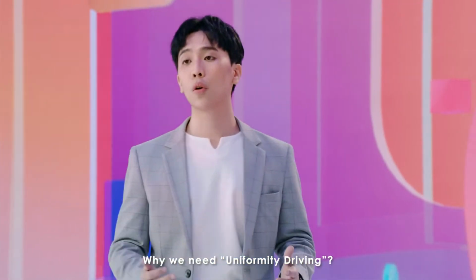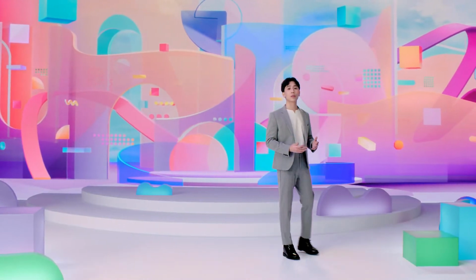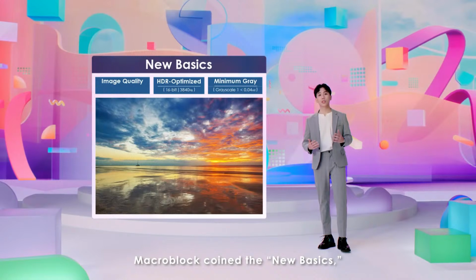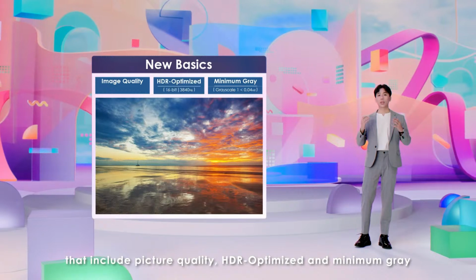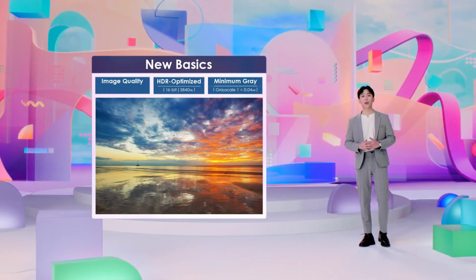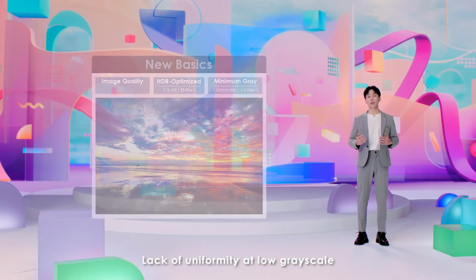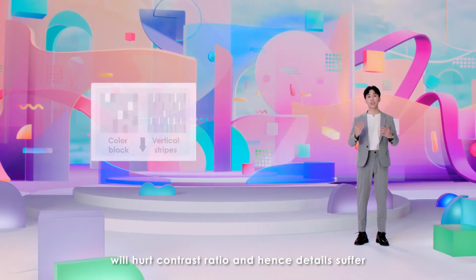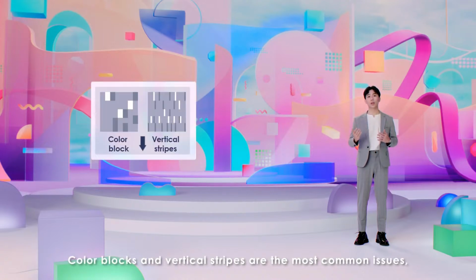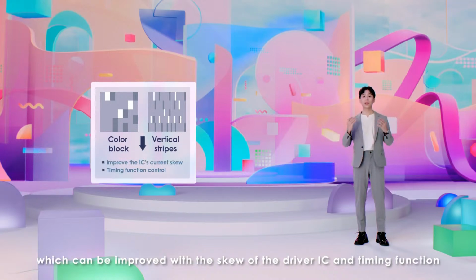Why do we need uniformity driving? Fine-pitch LED displays are very demanding of display performance. Macroblock coined the new basics, which are standards for fine-pitch displays that include picture quality, HDR-Optimized, and minimum gray. To meet the specifications, excellent display performance at low grayscale is the key. Lack of uniformity at low grayscale will hurt contrast ratio and hence details suffer. Color blocks and vertical stripes are the most common issues, which can be improved with the skew of the driver IC and timing function.